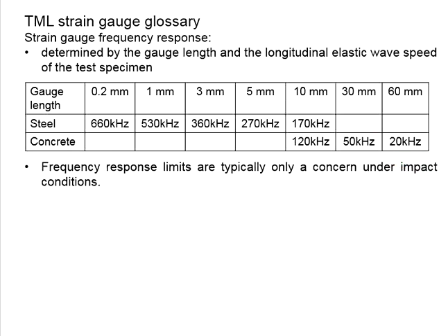It means that the specimen is subjected to a sudden or instantaneous load where the magnitude increases significantly within a very short period of time. Now you will need high frequency response in order to extract sufficient data throughout the short period of impact.